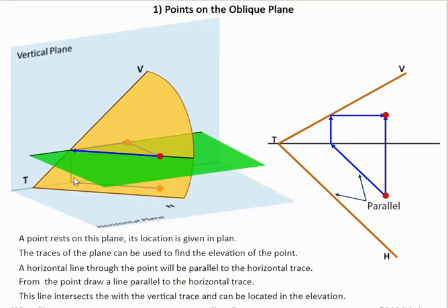Now again, this is the construction shown in the 3D graphic. The same construction here, bringing it up here. So this is how you find a point from one view into another view. If you're given a point in plan and you need to find it in elevation, this is the construction method. The line here goes parallel to HT, then it's brought up vertically and then horizontal, as in all orthographic, but it is a point in plan, that point is directly straight up in elevation.